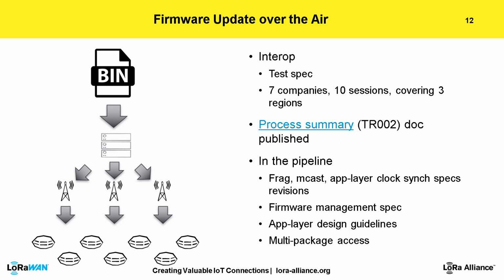We also have a firmware management spec. This is another application layer protocol that helps us manage the firmware file on the end device, like checking its version, deleting it, or rebooting the device to activate the new firmware. And while doing this exercise, we also built some good experience around how to build applications for LoRaWAN.